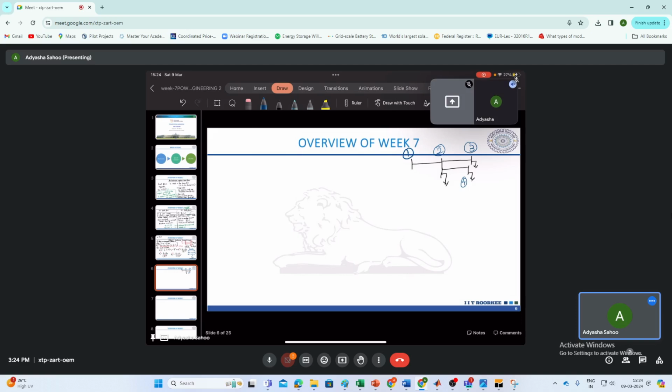So writing the KCL at bus 3, I will get the current here flowing from I2 to I3. So that is same as this load current here, I3. So this is I3, this is I4, this is I2. Small are the load currents and capital are the branch currents.